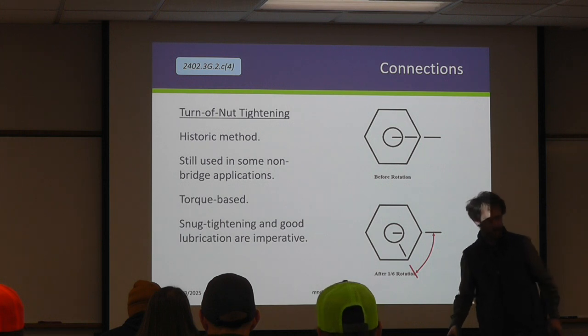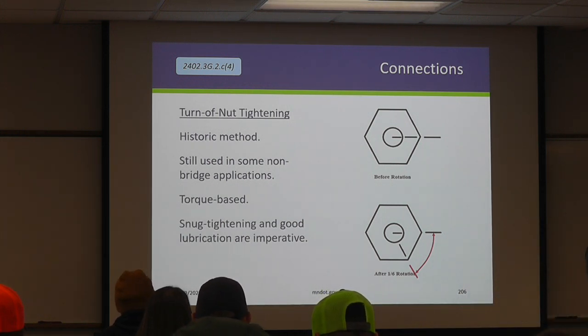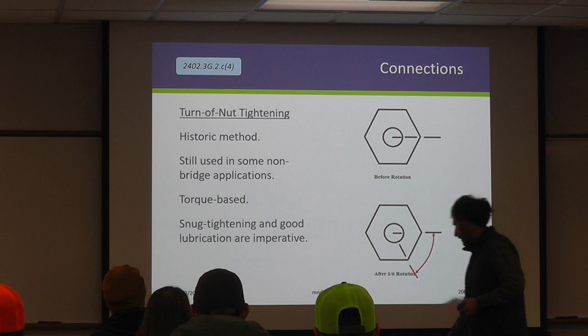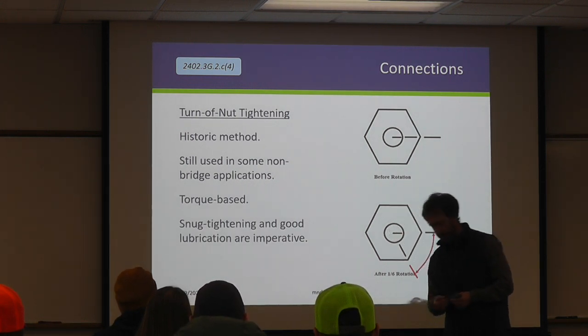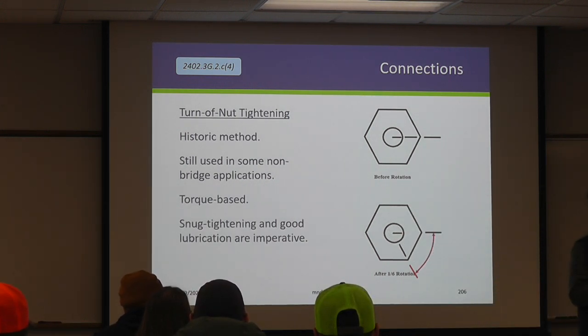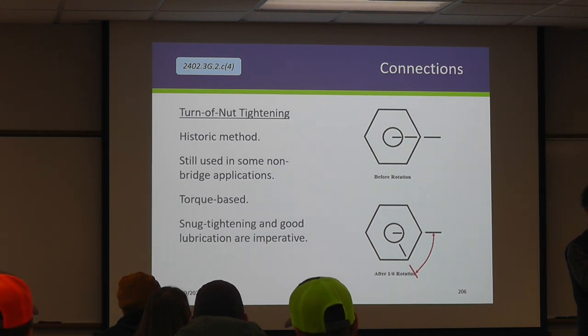Okay, I'm gonna pass this assembly around. This is installed in the correct order. One thing I will pass along with it are these feeler gauges. And so what I would like for you to do as it's coming around, just see how these would potentially be used. Obviously, you're going to have steel in the way, so you'll push your DTI against your nut and see how you will insert them. Note that this particular DTI has these little bumps in it, if you will, along the perimeter. That's to help you locate where the feeler gauge is supposed to go. Not all DTIs have that. It's a pain in the butt when they don't.